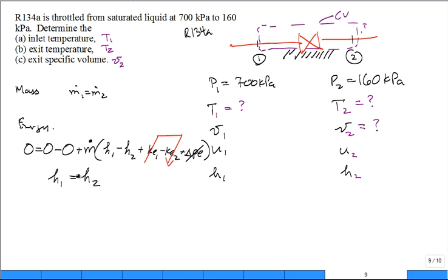It seems like a dead-end conclusion, but it's a very significant conclusion. If you look at temperature 1 and temperature 2, is the flow through this device isothermal? Is temperature 1 equal to temperature 2? No. Is it isobaric, the pressure the same at inlet and outlet? No. But it's isenthalpic. Isenthalpic, a new word, meaning the enthalpy in is equal to enthalpy out. It's not isochoric, not isobaric, not isothermal, it's isenthalpic. So that means the enthalpies are the same.